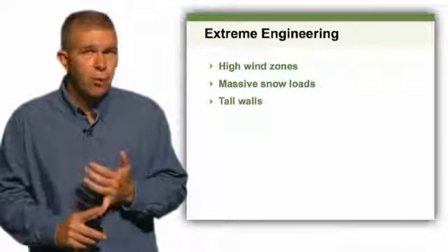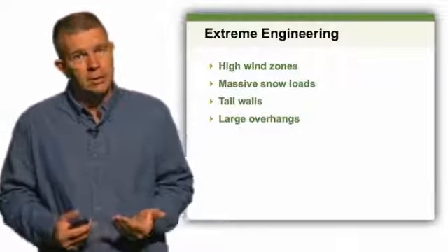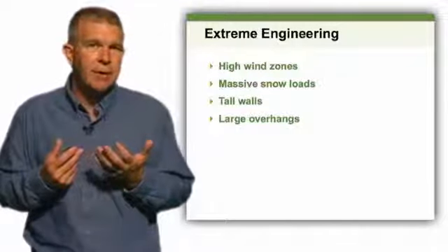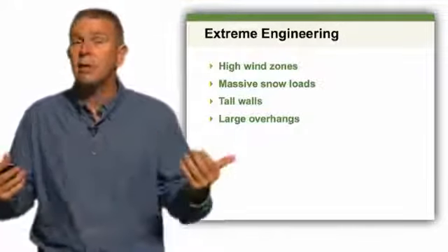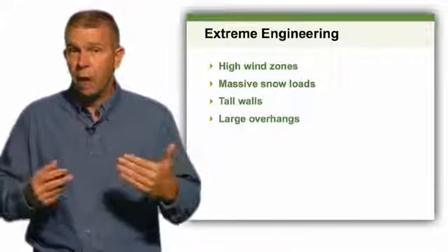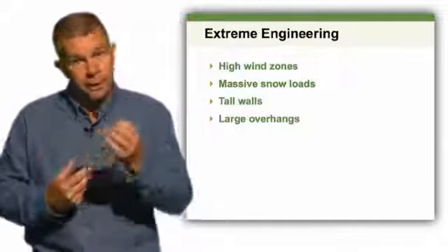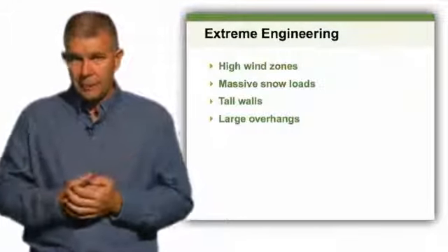In addition, if you get really high tall walls or you get massive overhangs, you have to start dealing with things like wind uplift. And it's this wind uplift that the designer needs to take into consideration to determine whether or not they have the proper fastening schedule, because if you don't have enough screws in your roof panels to overcome the wind that hits that building and then tries to rip the roof panel off, you're going to have a problem. It's these types of things that you need to be paying particular attention to.